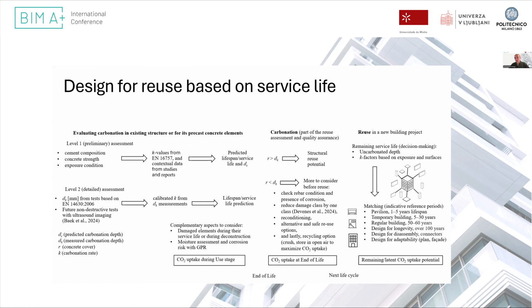The proposed approach in the paper could also be used to design for use. By considering whether we need to extend the service life of elements to match them with the new recipient building, we could look at different strategies to extend their service life by protecting the elements. Perhaps if they are used outdoors, with a hydrophobic coating against moisture and water, or if they are used indoors, perhaps using plasters and coverings that would further reduce the carbonation rate.